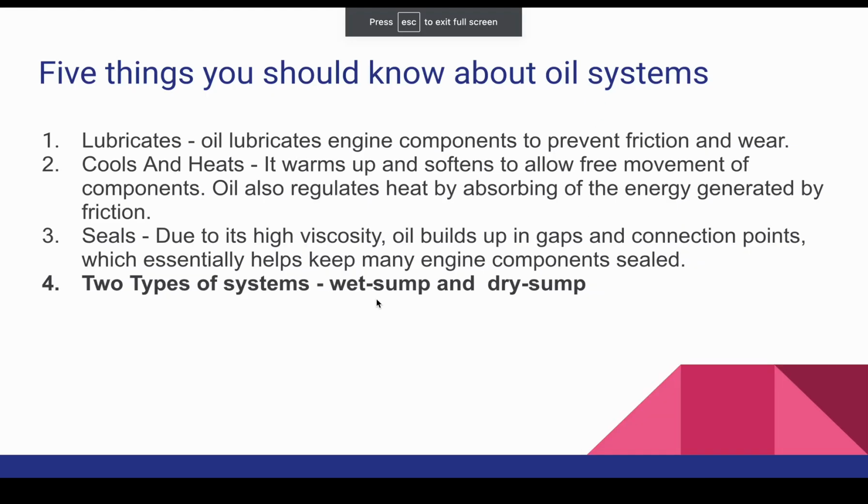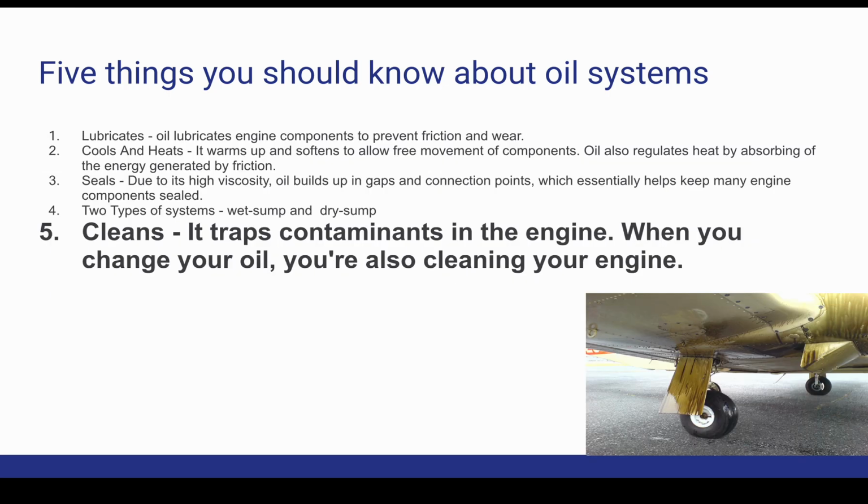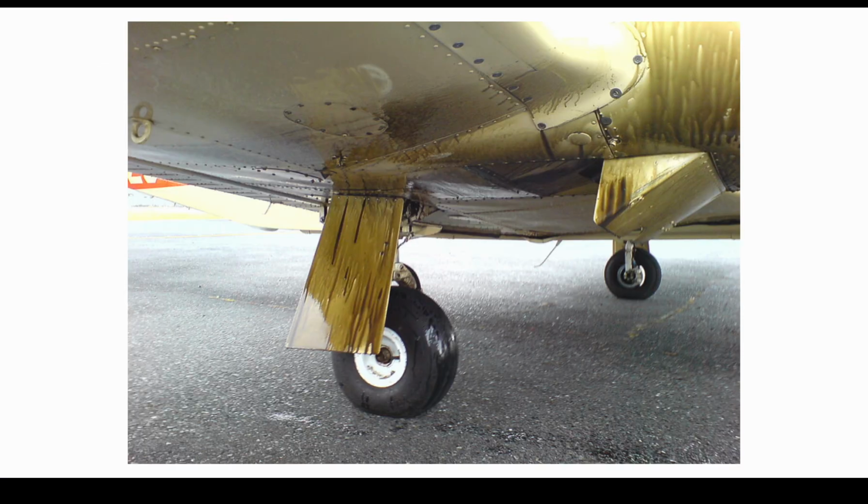Two types of systems: there's a wet sump and a dry sump system. The one in the 172 that we've been talking about is a wet sump type system. And it cleans, it traps the contaminants in the engine. And so when you change your oil, you're also cleaning your engine.